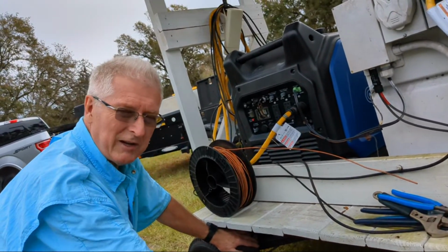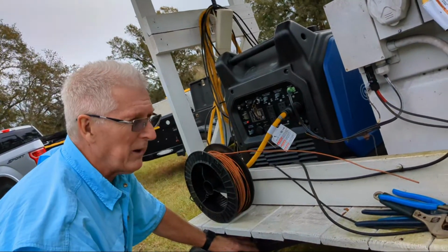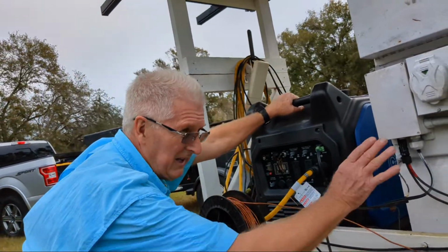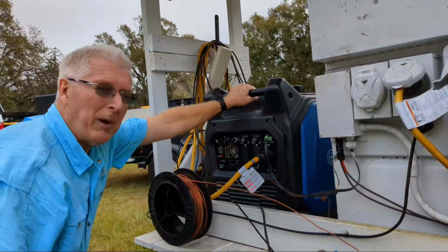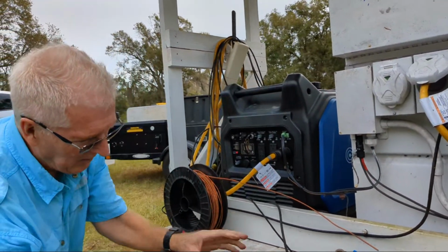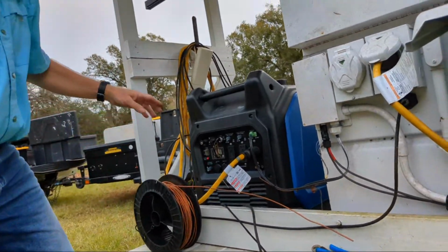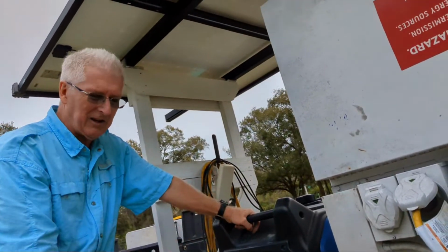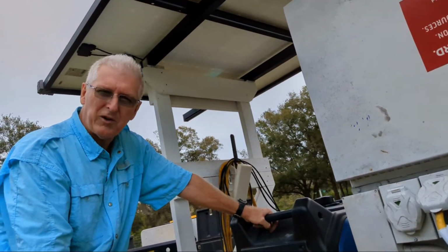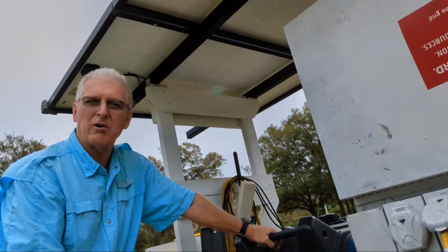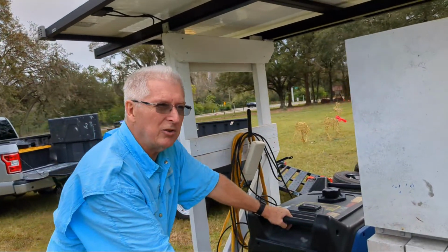We don't want this trailer to be energized. We simply want, in this particular case, if there was to be a fault in the generator or in this power system, a fault path to earth. And unfortunately, we don't have one here. So the easiest way for us to do that, when it's by itself, is to give it a fault path to earth. That means some type of earth connection that we can drive in the ground, specifically something bonded to our electrical system ground.